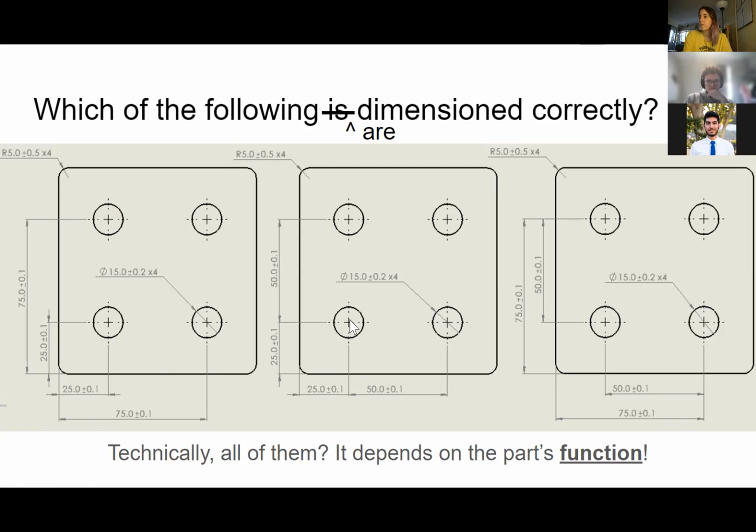Versus if you look at the middle one and the right one, we care way more about the holes being 50 millimeters apart than we do, say, how far they are from the edge. So that's just to reiterate the important part about how you have to consider what the function of your part is while you're making this drawing, because though they're pretty similar, the difference comes up